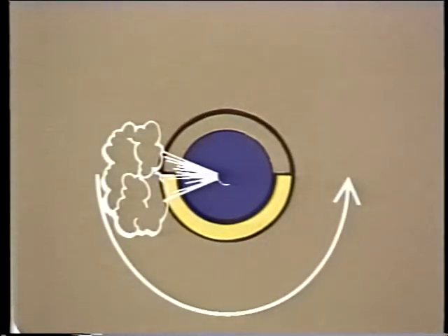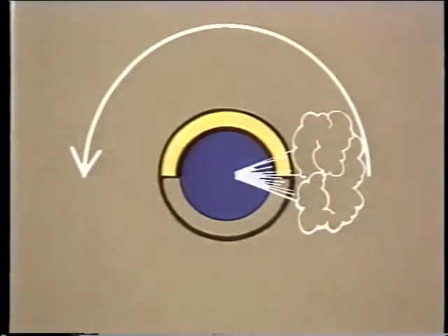The blowing medium can be directed over a full 360-degree circle, or if the part of the cam that the valve trigger rides on is cut a little, the arc the blowing medium follows will be shortened accordingly. The more that's cut off the cam, the shorter the blowing arc. You can also see from these examples that if the cam is turned around, the blowing arc moves around too. Changing the orientation of the cam like this is called indexing the cam.